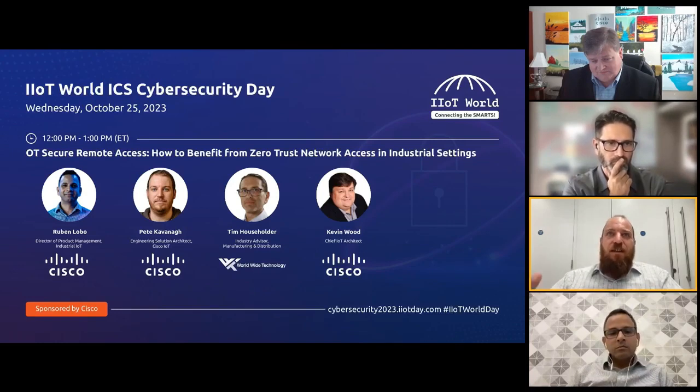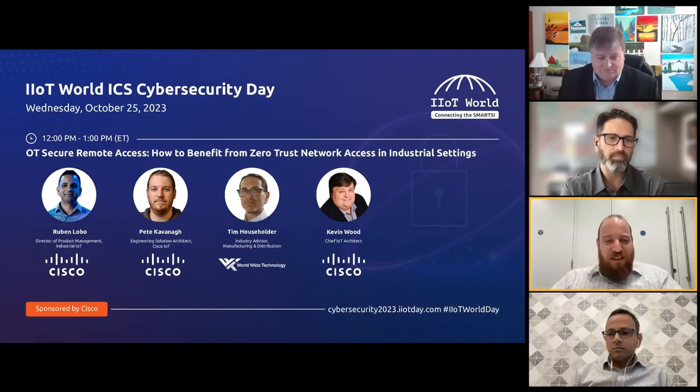But they've done it in a way that from every other respect is really not a best practice. The one thing that really jumps out at me there is they'll buy a generic cellular modem. They'll spend money on a premium SIM card that gives them a public IP address on that WAN interface, and then they'll do port forwarding directly in from the dirty public internet, right, through to their critical infrastructure